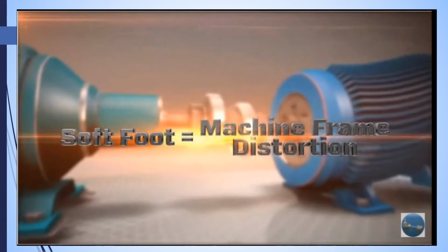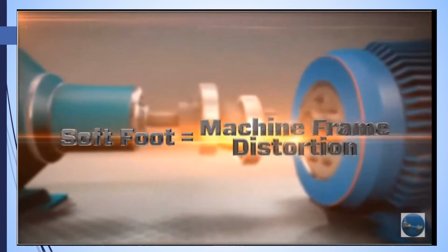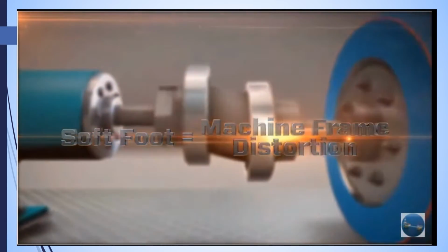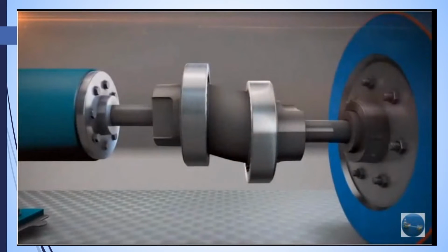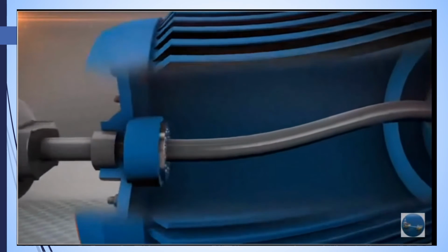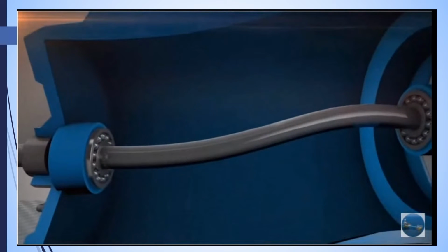Soft foot means machine frame distortion that occurs as the machine's hold-down bolts are loosened or tightened. Distortion of the machine frame leads to misalignment at the coupling, internal misalignment of the bearings, increased radial load on the bearings, and a deflected shaft. Therefore, a soft foot condition creates two inflection points on the shaft, which produce vibration as the shaft rotates.